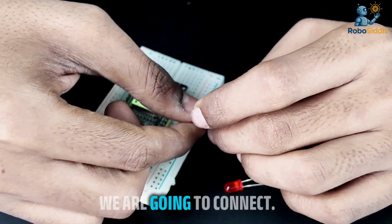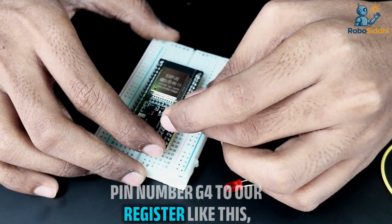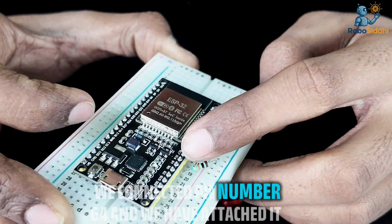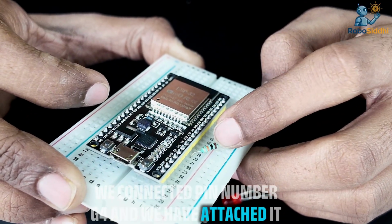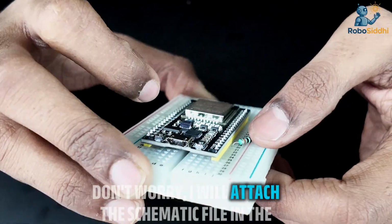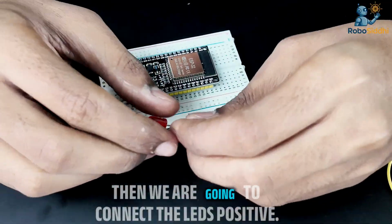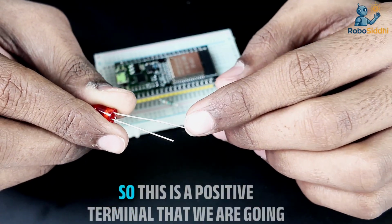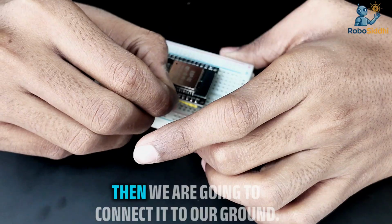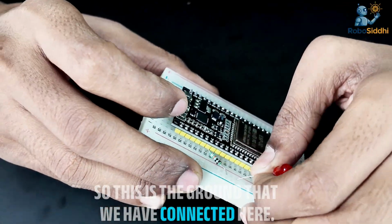First of all, we are going to connect pin number G4 to our resistor like this, right? Just like this. We connected pin number G4 and attached it to our resistor. If you don't understand it, don't worry, I will attach the schematic file in the video description. Then we are going to connect the LED's positive. Then we are going to connect it to our ground. So this is the ground that we have connected here.